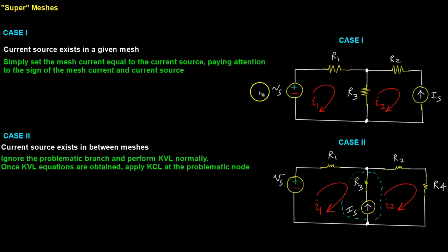And if you recall, a voltage source will give you the necessary, defined voltage no matter what the current through it is. And so that is not a problem for KVL or mesh analysis. Now, if you add a current source, that is where things get kind of tricky, because the voltage across a current source is not known.